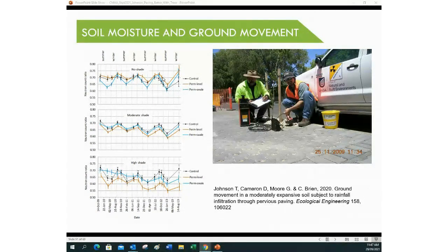So one permeable design was wetter, the other permeable design was drier. That tells us we need to do some more research, and it'll be climate dependent research to determine the optimum depth for integration of nature into the cities. The depth of the gravel base does make a difference, but what's interesting is it can be wetter, can be drier where there are no trees.